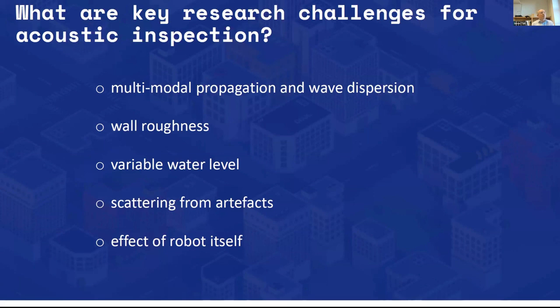The advantage of this higher frequency propagation is that it's able to pick up defects with much more fidelity. Also, with any wave process, the wave itself disperses as it hits joints, lateral connections, and imperfections in the pipe itself. So issues such as wall roughness reduce the energy in your reflection. As I said before in the slide, the acoustics feel everything inside the pipe. So they feel the pipe wall, they feel its joints, its defects.